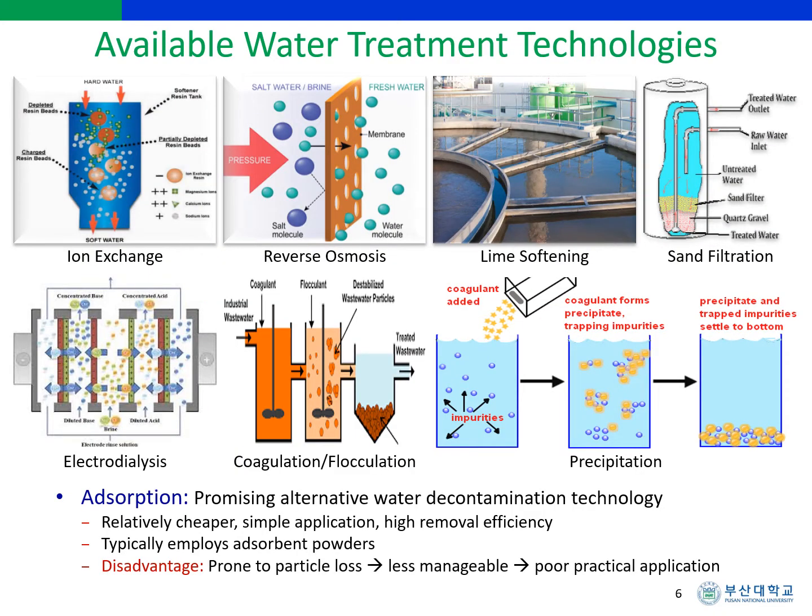The best available small system technologies compliant with the United States Environmental Protection Agency implementation guidelines for radionuclides for strontium-90 removal from water are ion exchange, reverse osmosis, lime softening, enhanced coagulation or filtration, green sand filtration, co-precipitation with barium sulfate, electrodialysis or electrodialysis reversal, preformed hydrous manganese oxide filtration, and use of activated alumina. Nevertheless, alternative treatment systems or techniques that can meet the maximum contaminant concentration can be explored and applied.